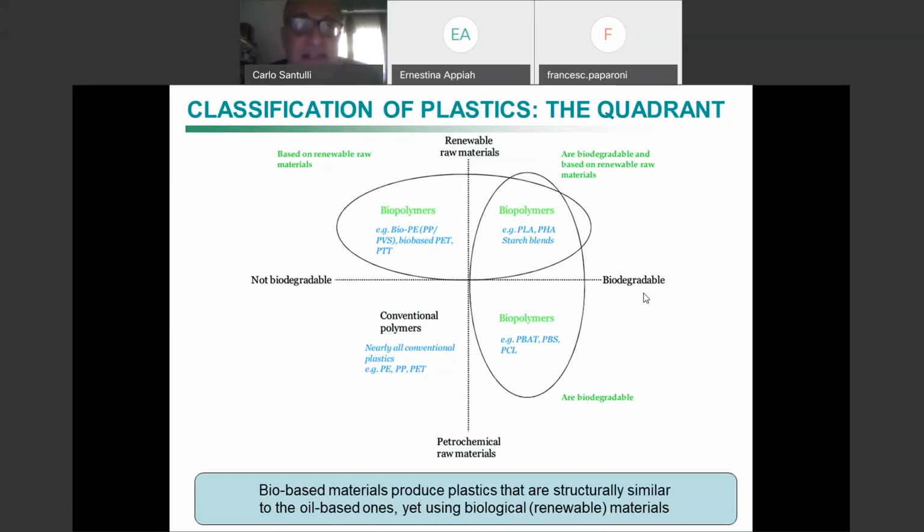We might have other chemically more suitable options like the creation of copolymers with some interaction, or we might just blend, put them together with no real interaction. I take 50% of that, 50% of that. For example, I can take 50%, this is quite popular, 50% polyethylene and 50% polylactic acid, PLA. And I get something which is sort of biodegradable but slow. I hope it biodegrades once I finish with it.